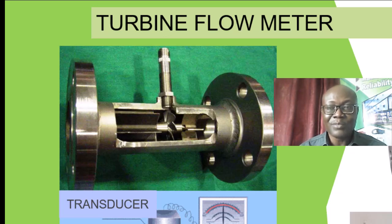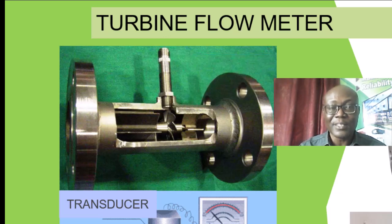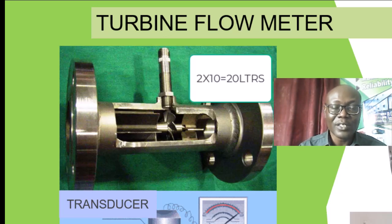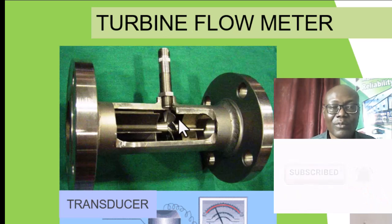Remember, we said between two pulses, a specific volume would have passed through the turbine flow meter. Okay, so let's say between two pulses, we have 2 liters that have gone through the turbine meter. So if we have 10 pulses, it means that we have 20 liters of fluid gone through that section of the turbine.